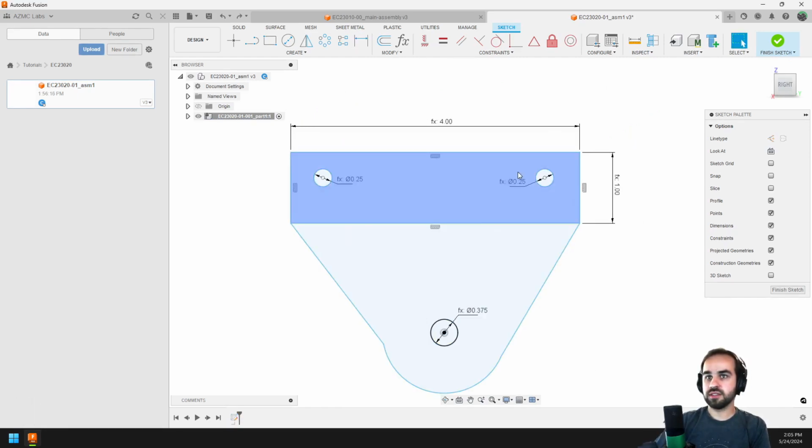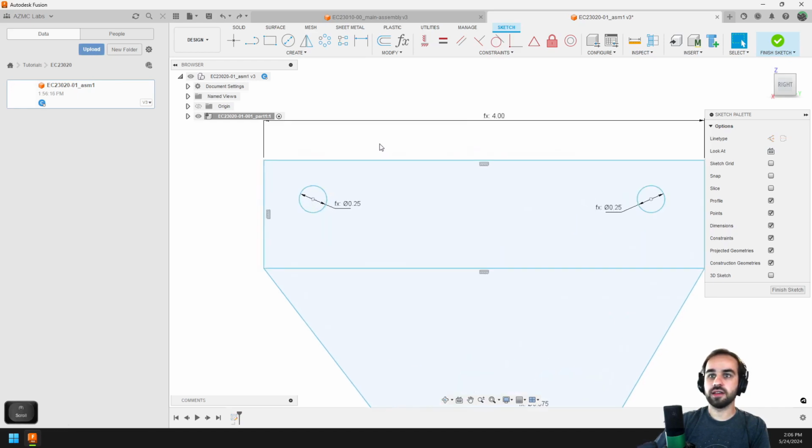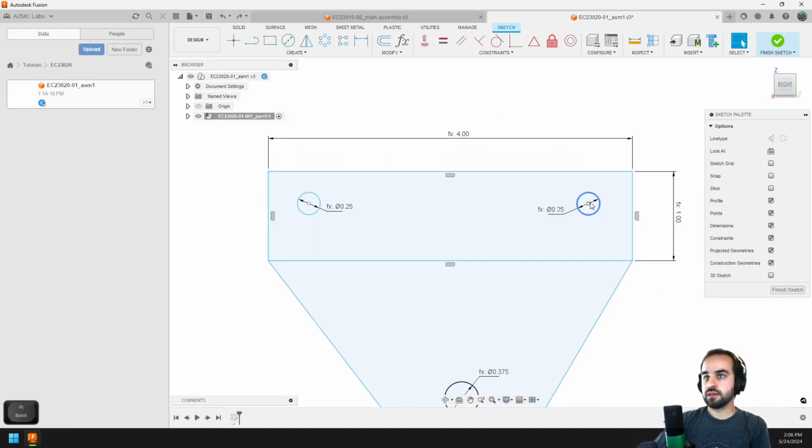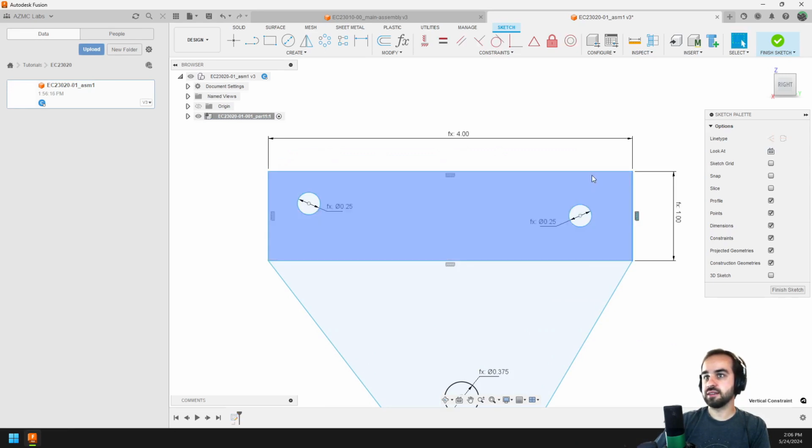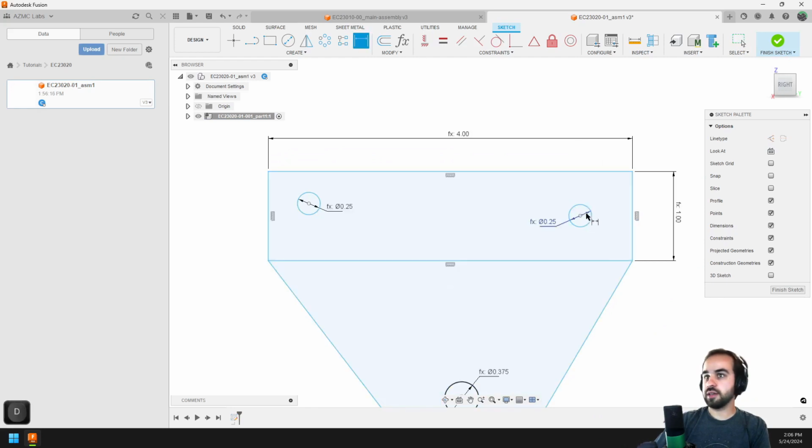Okay, then before we position this, let's get these locked to the mounting area. So let's say these should be halfway on this dimension and then the same distance from the end as they are from the side. We can do that using the parameter we created for the height. So selecting that center point and the side, we can type in mount height divided by 2.